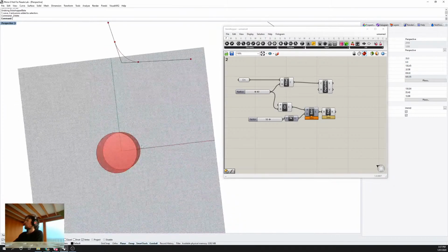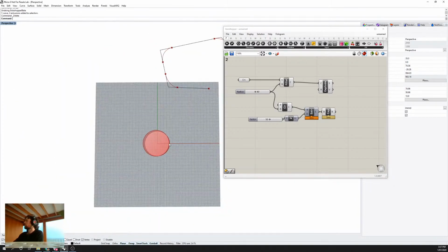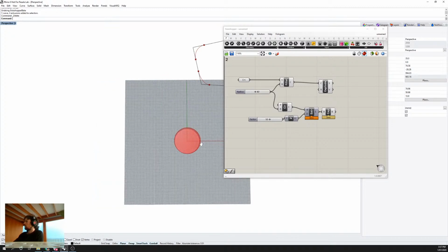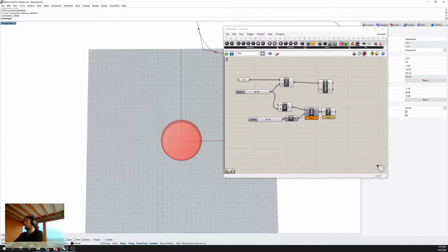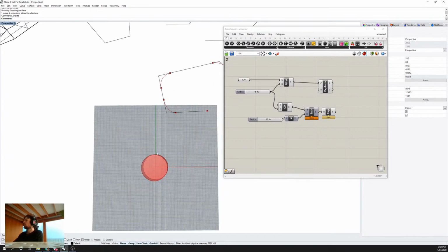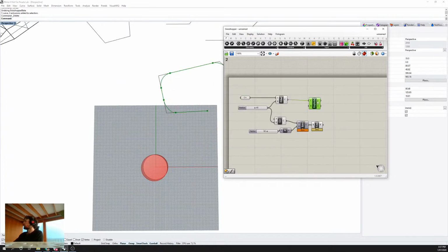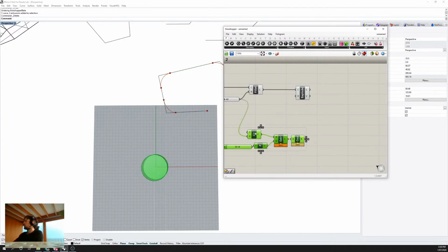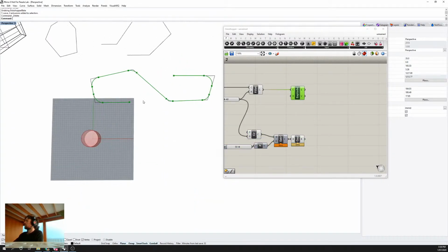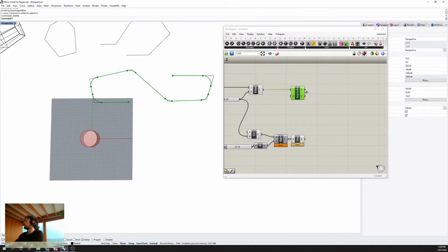Okay, there's our bender. And to simplify things later on, I'm going to move this bender preview just over a little bit so that rather than the bender being centered, oh, actually no, I'll leave it there, it's fine. So this is our bender radius, right? So we've got our part, we've got our bender preview, and the next step is to orient this part onto this bender, one bend at a time. Now we can do this the really simple way first, and then we'll gradually introduce a bit more complexity to make it more like the actual bending application.